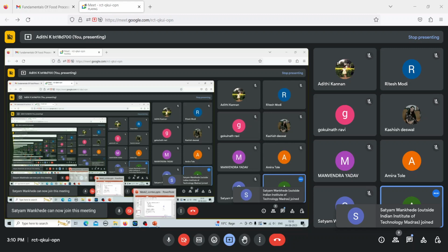Now the third statement: the net force is gravitational force minus buoyancy force plus drag force. Is that net force equation correct or wrong? Based on the direction of the forces that I just discussed, what should be the answer? Statement third is false, because if your ball is dropping like this, you have gravitational force acting downwards, and drag force and buoyancy force acting upwards. So the net force is gravitational force minus buoyancy force minus drag force. So this should be minus. So statement third is also incorrect.